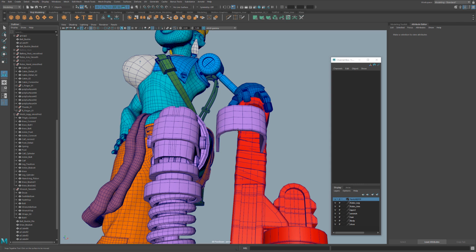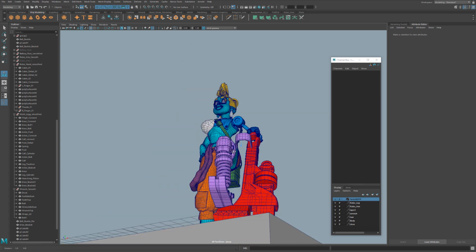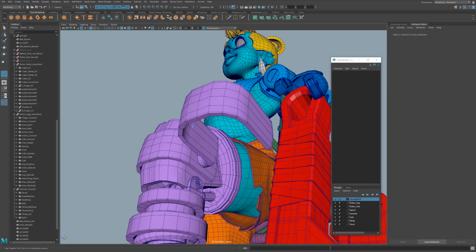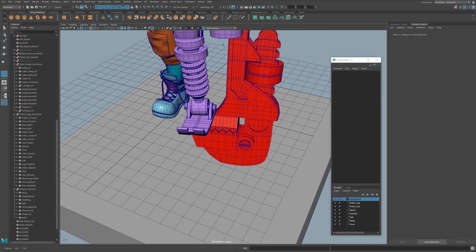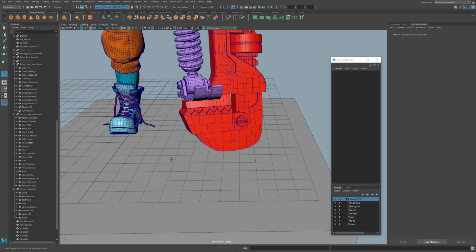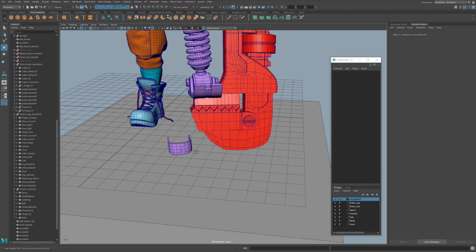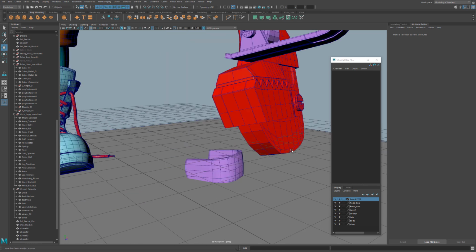We can click this face here, and you see that the little arrow is going to be activated, right? So that's the face that it's using. And then it's going to snap together to whatever other face we select. So I'll select this face here, I'll hit enter, and you see that it snaps.